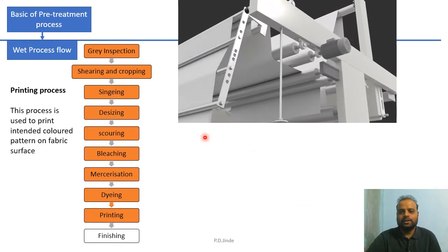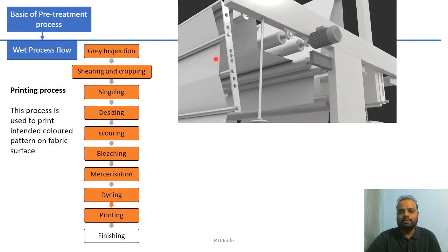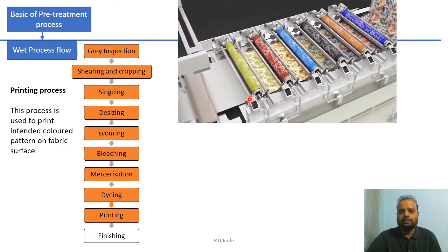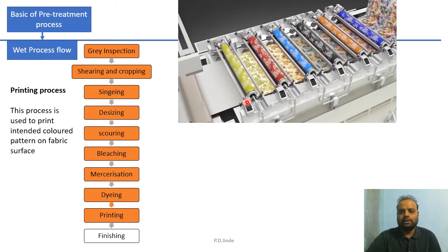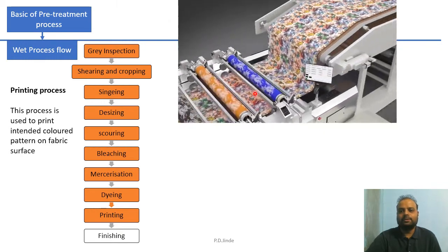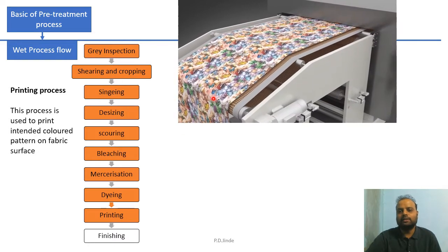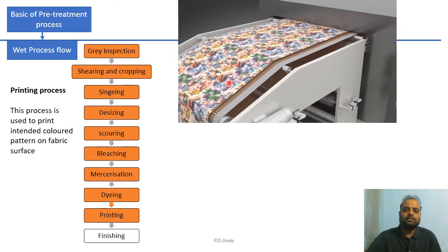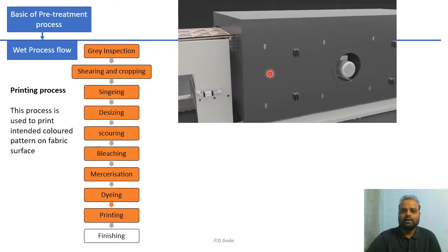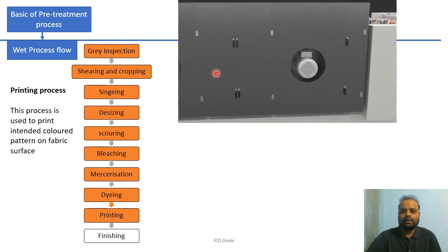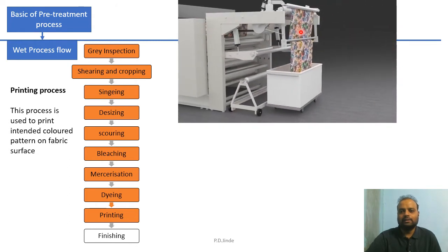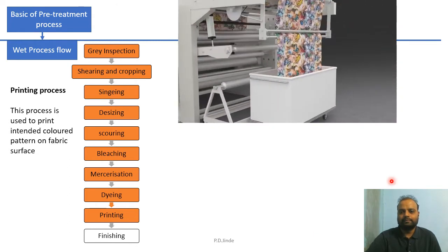This is a bleached fabric, you can say, mercerized fabric, white in color, guided over the guide rollers and ultimately under the roller printing, or rather screen printing, circular screen printing, and then the printed fabric passes over the conveyor belt. Here, this is a dryer where fabric is dried, steamed and ultimately piled up into a container.